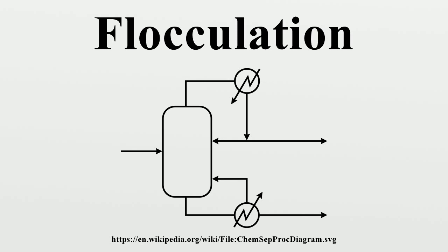in the suspension. Coagulation and flocculation are important processes in water treatment, with coagulation to destabilize particles through chemical reaction between coagulant and colloids, and flocculation to transport the destabilized particles that will cause collisions with floc.